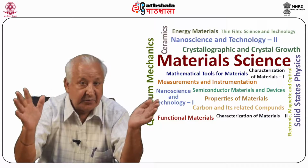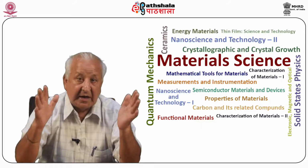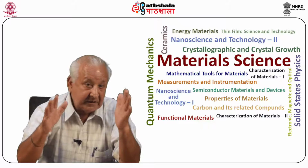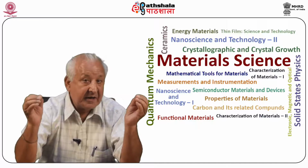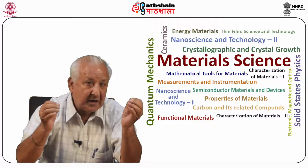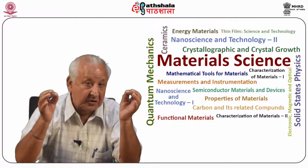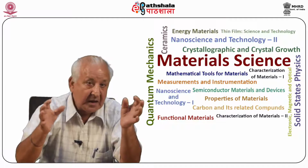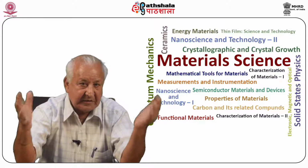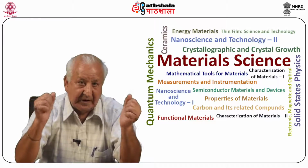In this case, it is important that the material does not have different densities in the solid and liquid phases. Suppose the solid material has lower density than its melt. The crucible containing the charge is likely to crack. However, if the solid has a greater density than its melt, it will lead to differential dimensions of parts of the growing crystal with respect to the crucible. These are the problems with such materials and can be overcome by some specialized techniques, which may, however, take the technique far from being a simple one.